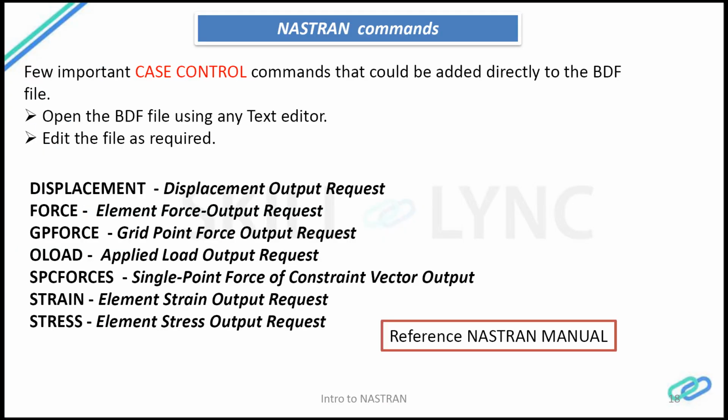Going into some of the important commands, from the output requests you can see DISPLACEMENT, and FORCE, which is the element force. GPFORCE is the grid point force, which is the nodal force, and OLOAD indicates the applied loading.